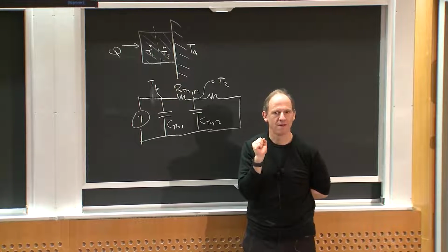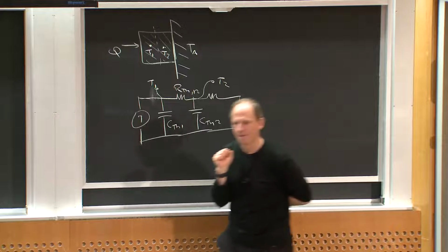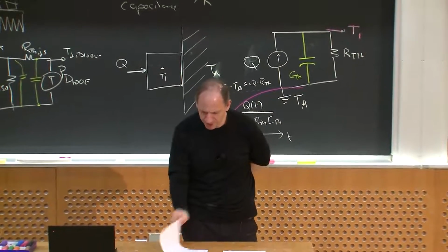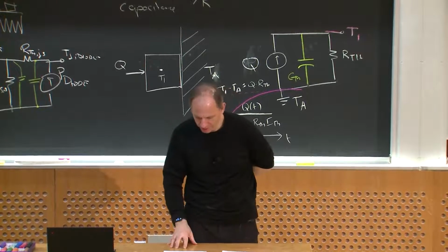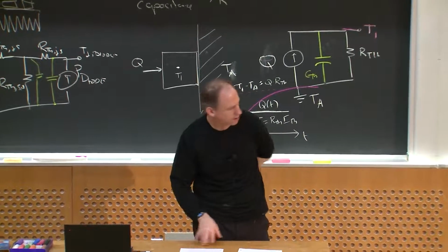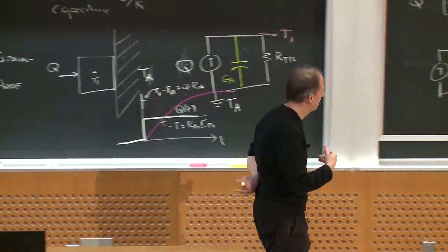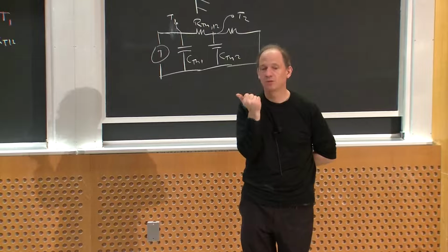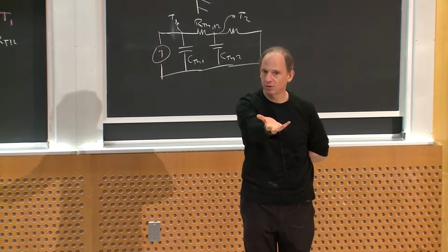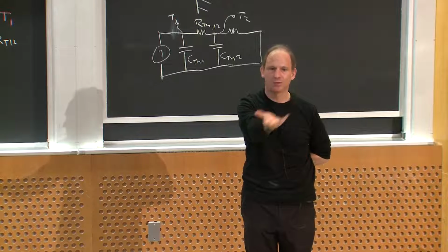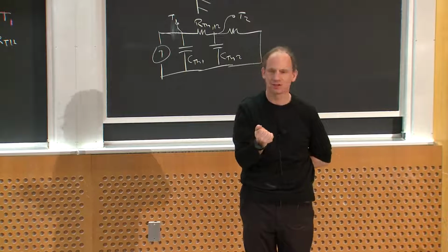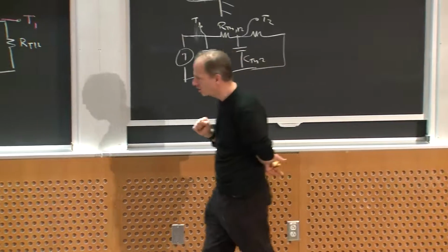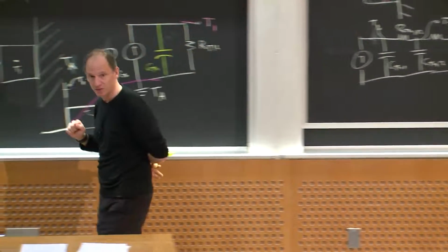Any other questions? Okay. How do people model, say, the thermal capacitance aspect? Sometimes you can look up, if you have a material, its heat capacity and then multiply by the mass, and you get a thermal capacitance. You can do it from fundamentals this way. That's not always the way they give it to you for a device.